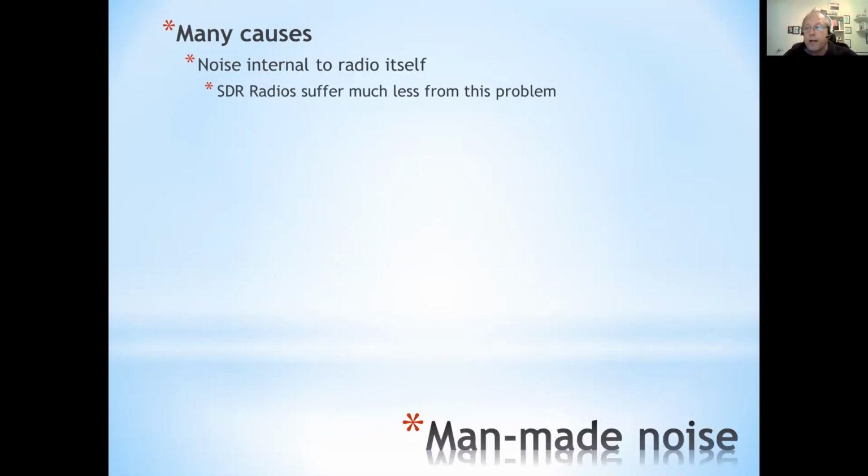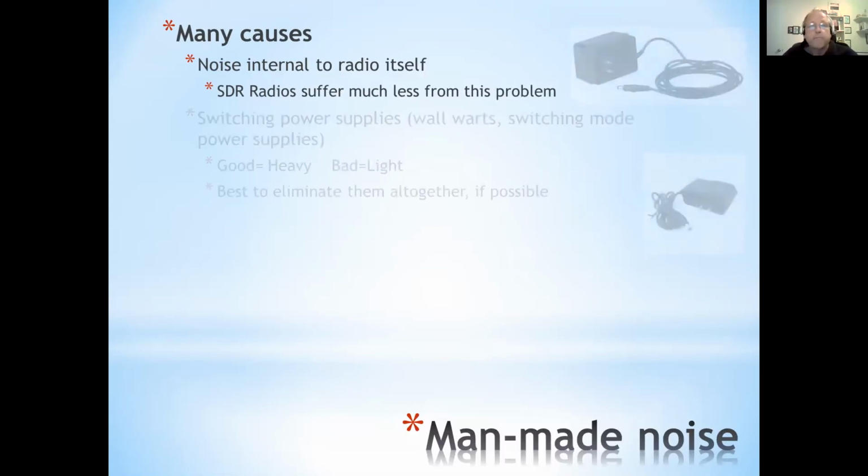A friend of mine bought a new Yaesu FT-3000 a few years ago, and I have both an FT-2000 and an even older FT-1000D. The FT-1000D starts putting noise out as soon as you turn the volume control up beyond 10%. On the FT-3000, the new SDR radio, you can turn it almost all the way up before you hear any noise at all until you hook an antenna up. So one of the advances of technology is that modern SDR radios themselves do not generate much noise.